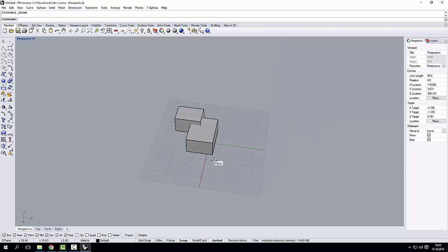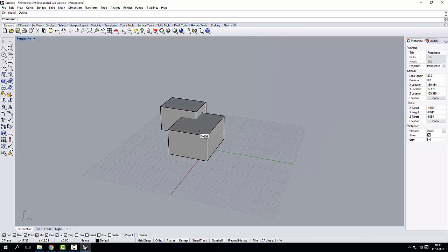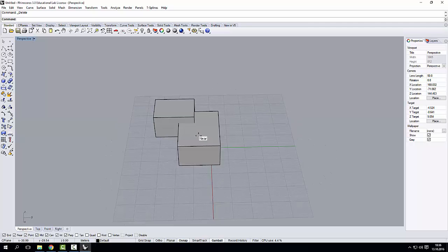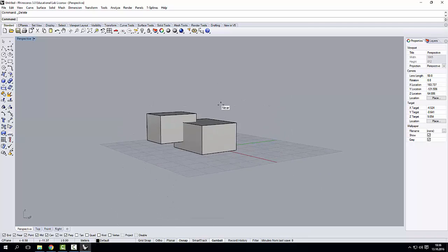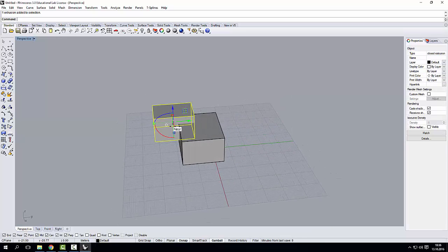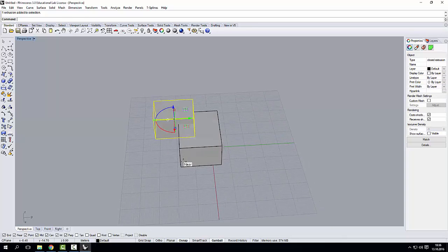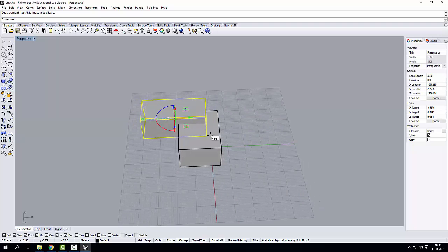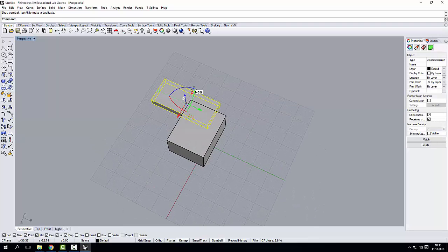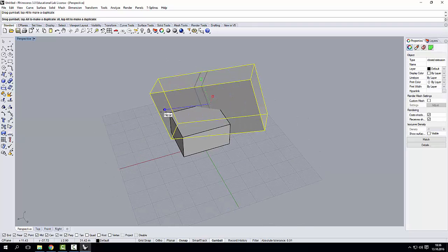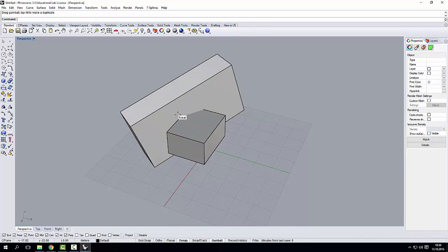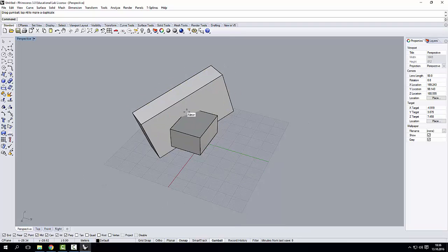And then we have the gumball, which is a very useful tool, especially if we are working on the first stage of design. The gumball allows you to select the geometry, you find it down here, and to modify it dynamically. So I can turn stuff, I can scale it. We're going to look at the gumball also in depth a little bit later.